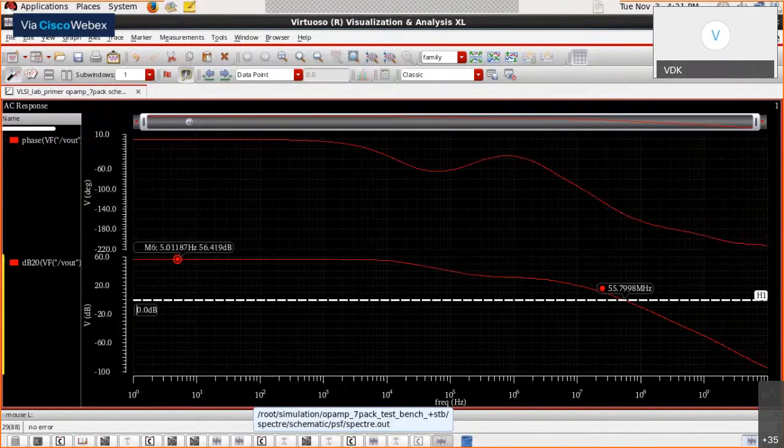Even in real designs, as I said, we do at least 3 different designs for the same set of specifications. The performance is matched. But then what we also end up doing, while putting up the data sheet, is going further conservative. Let us say I get a gain bandwidth of something like 100 megahertz, even tested on silicon or in my simulations, but in my data sheet I specify it as maybe 80 megahertz. So I'm acting safe.